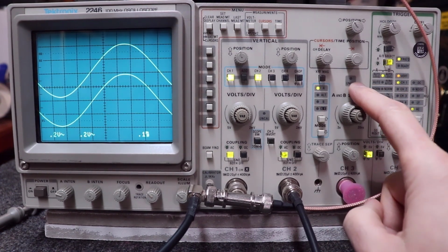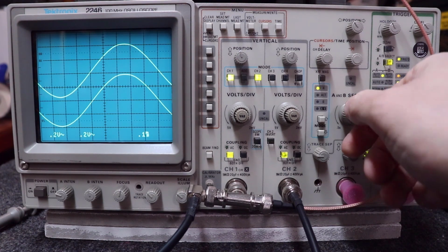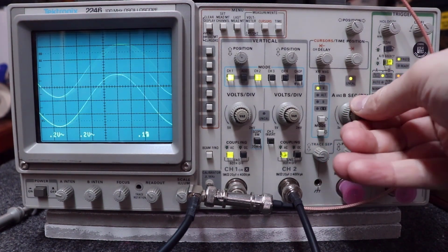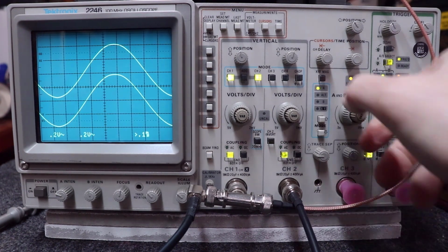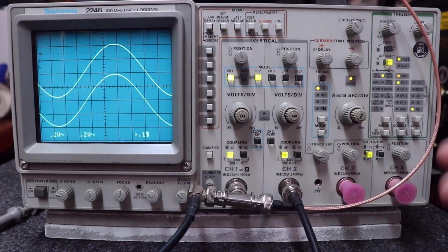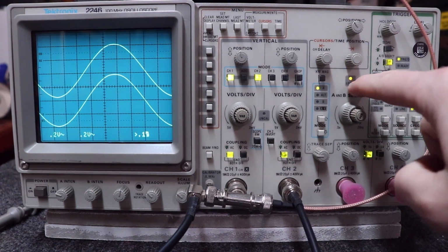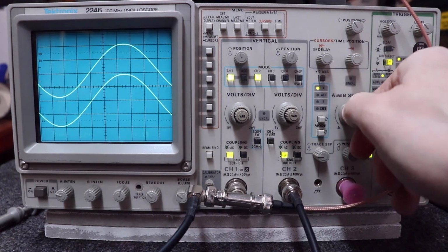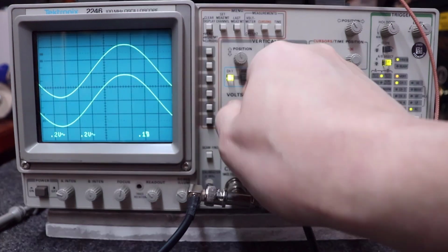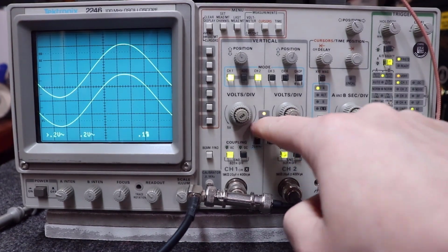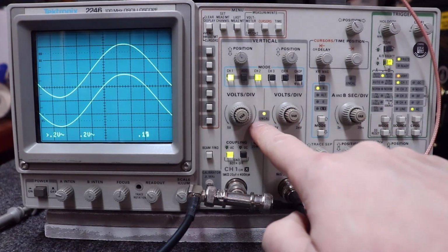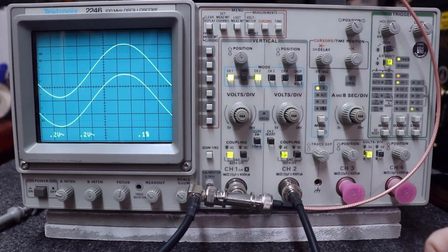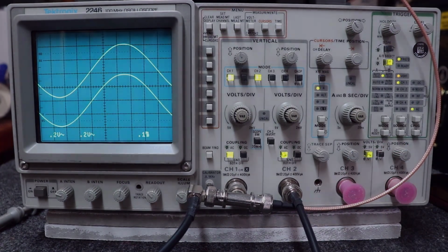This little light here will come on to indicate that you're on variable. Like, what happens if you accidentally hit that little button and you didn't notice it? You're over here playing with things, and you're like, God, things don't seem right. This little light just tells you that you're on variable. In other words, you're not locked in on a calibration. The same here. If you happen to bump that and get it off, this little light comes on to tell you that you're not locked into a specific voltage per division.